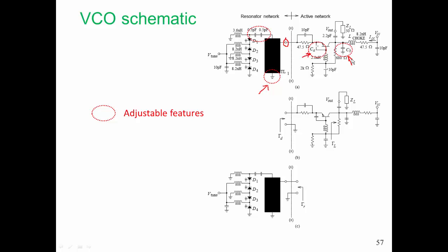So we're going to use it to shape the reflection coefficient curve. We introduce CA and CB in part to accommodate the frequency-dependent parasitics of our active device. That inductor at the base is the inductor in the Colpitts oscillator design. It's shared between the output network and the input network. But that inductor has an impedance that varies with frequency, so the amount of feedback varies with frequency.